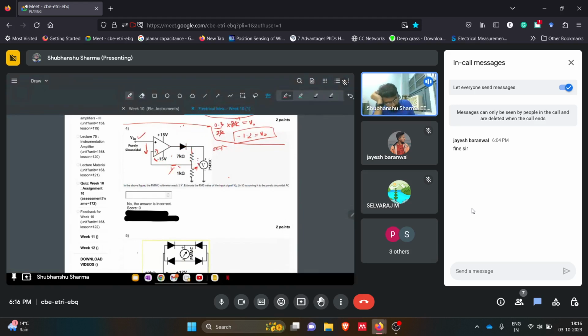So first of all, this op amp will act as a comparator, because we don't know whether feedback is there or not; that will depend on the diode's position. So we gave this sinusoidal voltage. This was positive, this was negative. If this is a comparator, then we can say this is grounded, because this branch is meaningless. So this is grounded, so this is 0 volts.